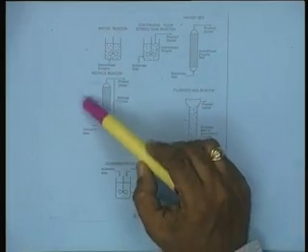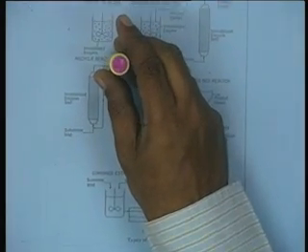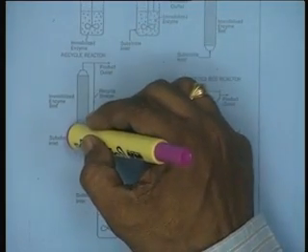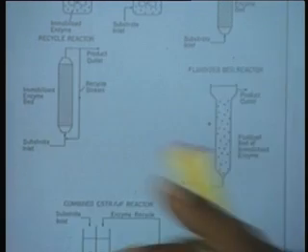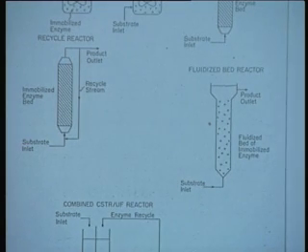Now, if you look at, for example, the case of the batch reactor as I showed. The second is the recycle reactor: if the product outlet is closed and the total stream is then recycled back into the feed, the whole operation can be carried out over a period of time, which is the batch reaction time.